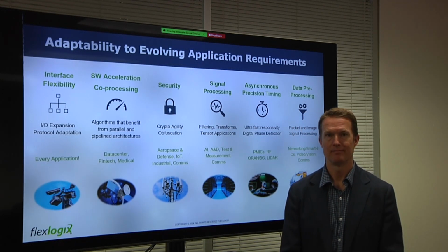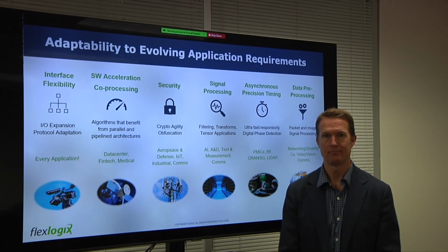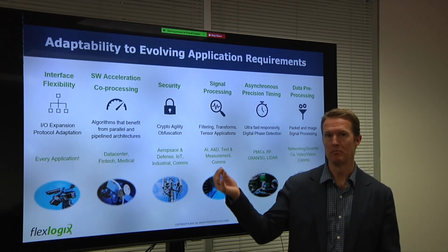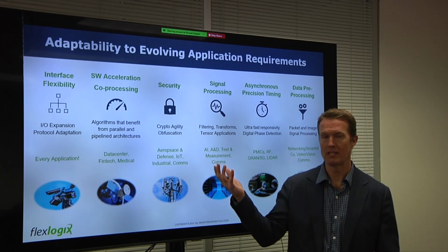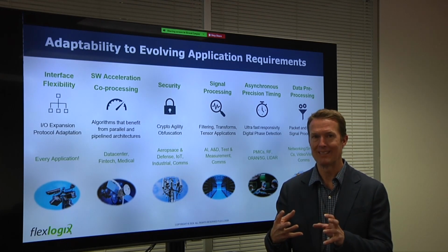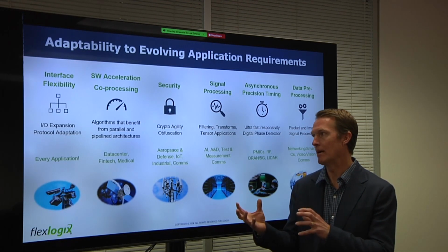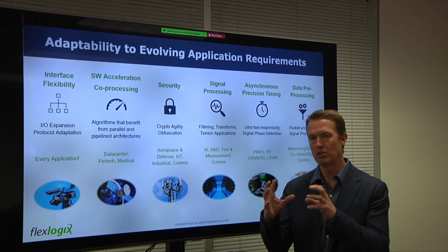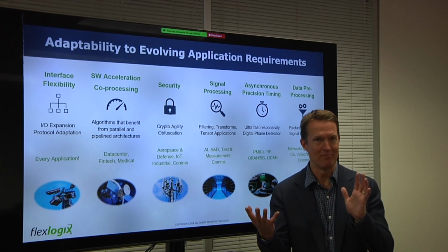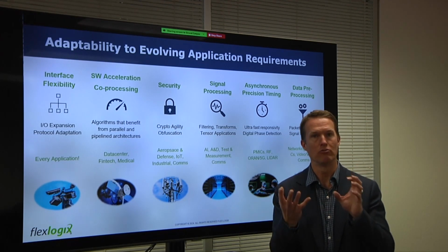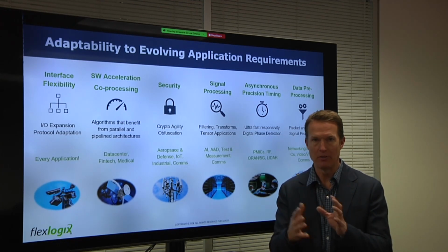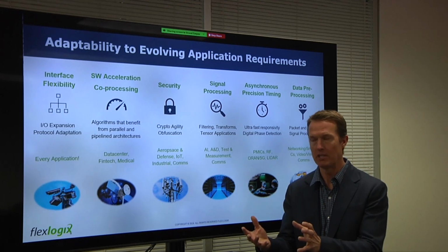There are certain things we know FPGAs do well, things like filtering, transforms. How does this apply now into the world of AI? Fundamentally, the building blocks that build those signal processing algorithms, whether it's filtering for FIR or doing FFTs, all those building blocks lend themselves directly to AI applications. And what really makes that marriage so great is not only the combination of high density and a high amount of multiply and accumulate modules inside the block, but also locally coupling memory to those blocks. Without the tightly coupled memory, you don't have the coefficient storage, you don't have the acceleration that you need.